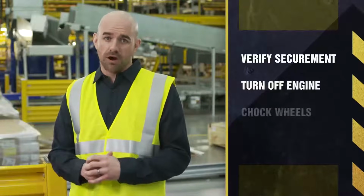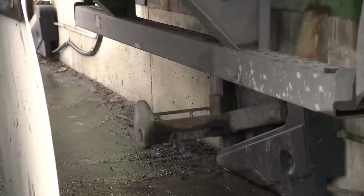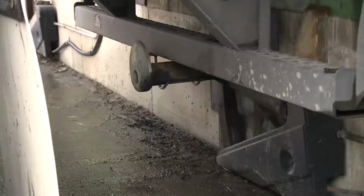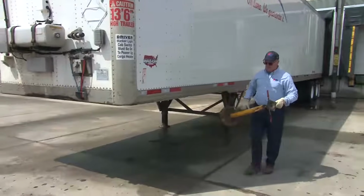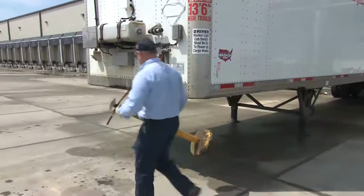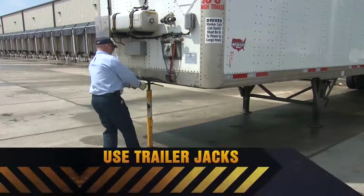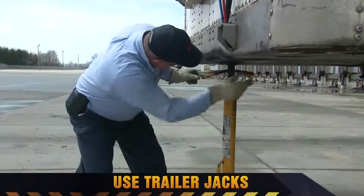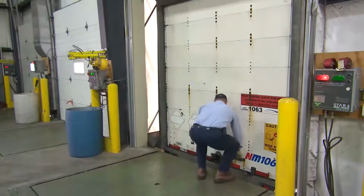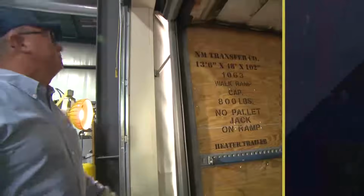Vehicle engines should be off, wheel chocks in place, the brakes of the vehicle should be set, and as a best practice, it should also be secured by mechanical means, such as a restraining system. If there's no tractor attached to the trailer, don't rely on the trailer's landing gear alone to keep it stable. When driving your forklift to the front of a trailer, use trailer jacks to prevent the trailer from tipping or collapsing. Open the freight doors to see if the trailer is well lit inside. Never use the forklift to perform this task.